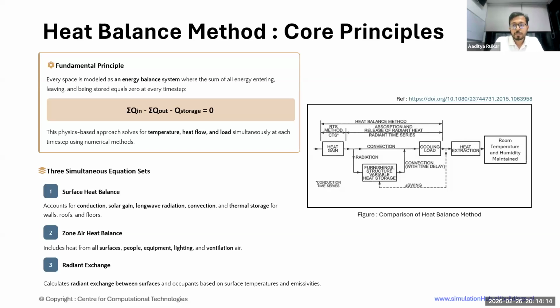The heat balance method takes this principle and applies it everywhere: to your walls, your windows, your zone air itself, or the internal mass within a space. So Q in, Q out, and how much heat is getting stored in that building component. That is the principle. It also accounts for time lag, as every component has some heat storage capacity. It stores heat and after some time releases it, which the heat balance method accounts for.